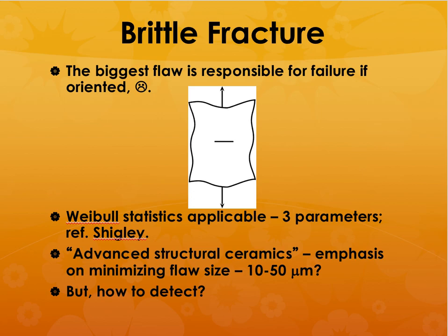So how do you make sure that the range of failure values of your samples reduces? The way to do it is by minimizing the amount of flaws and minimizing the size of those flaws.